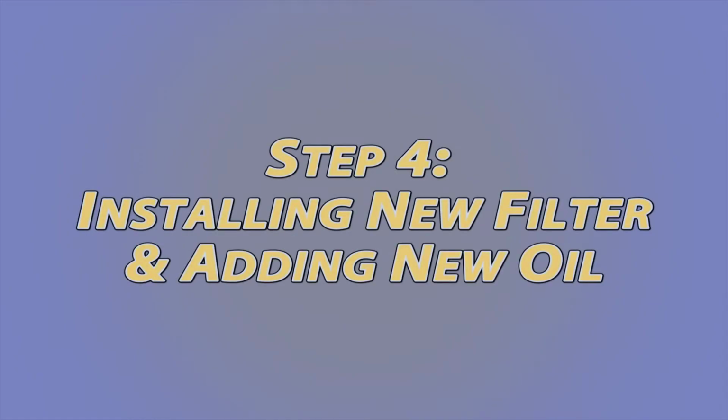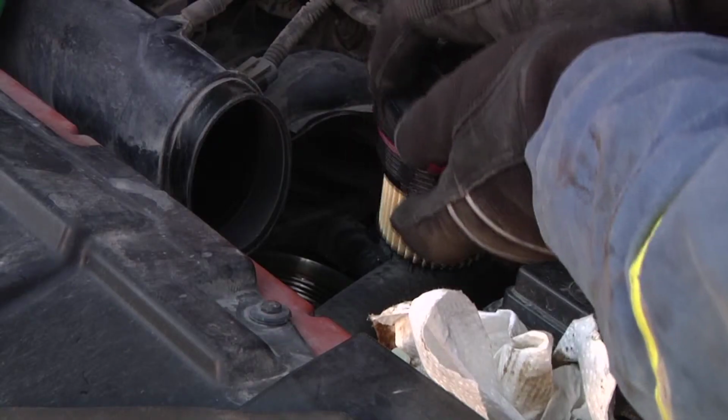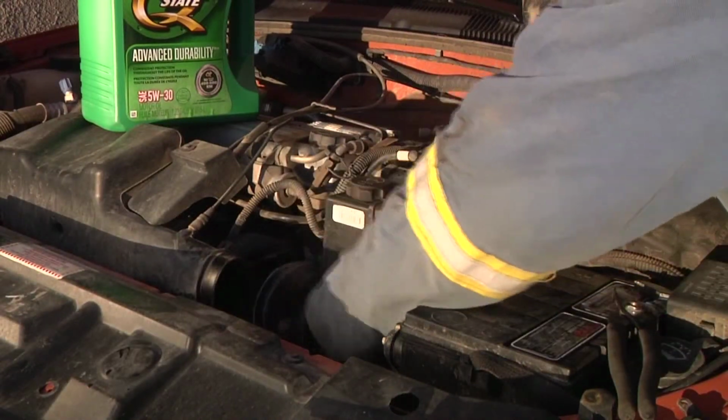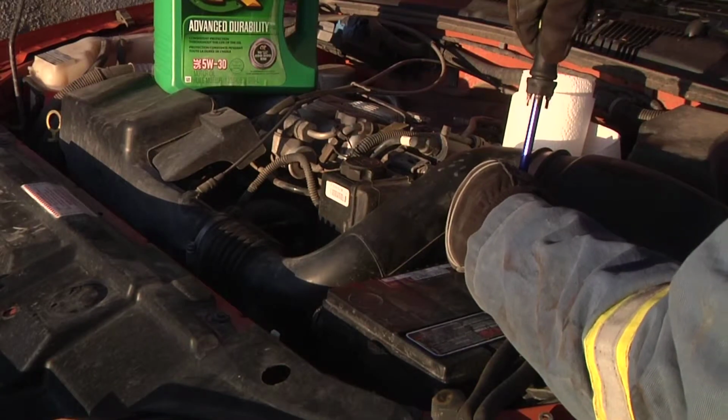Step 4. Installing new filter and adding new oil. In this step, we'll be installing the new oil filter and adding the new oil. Let's start by installing the new oil filter. Remember again, not to over-tighten. After that, clean up any residual oil that has dripped and leaked on any areas. Then replace the air intake snorkel.